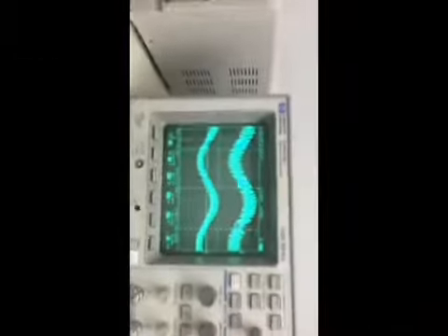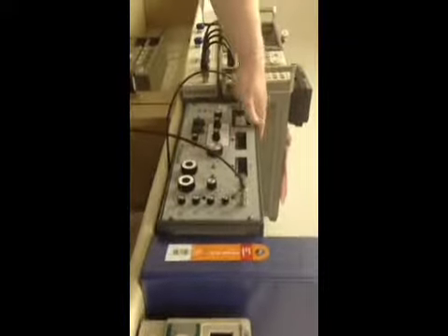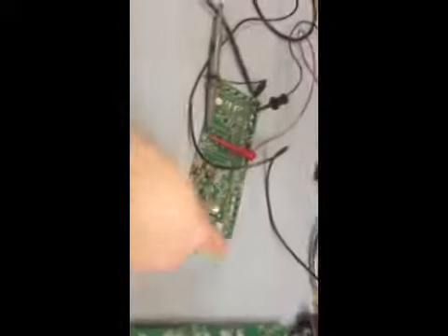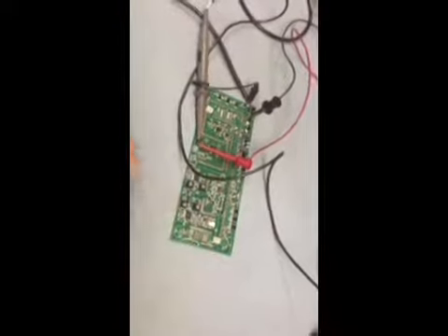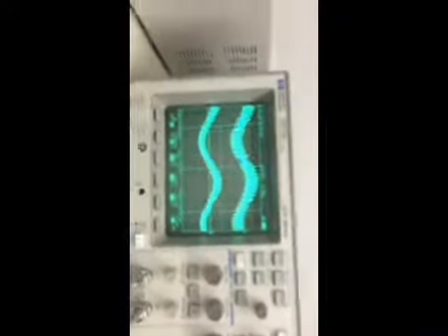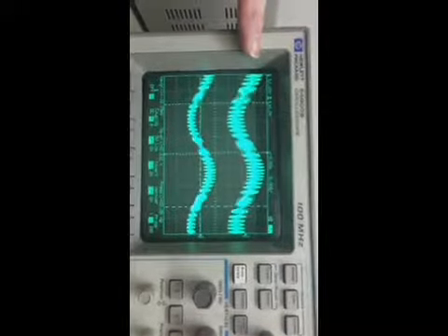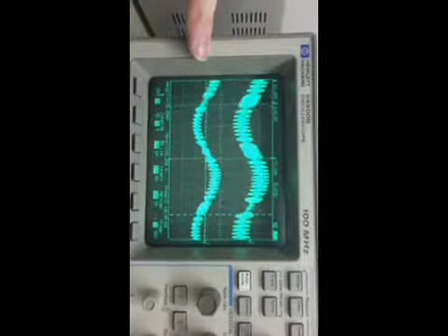Alrighty, this is our receiver receiving a standard VOR signal from our generator here, going in through the antenna cable, following along this microcircuit path here into the demodulator and being demodulated in the system. We're receiving it at minus 55 dBm, and the signal that's being generated is up top here. The signal that's being received is down below.